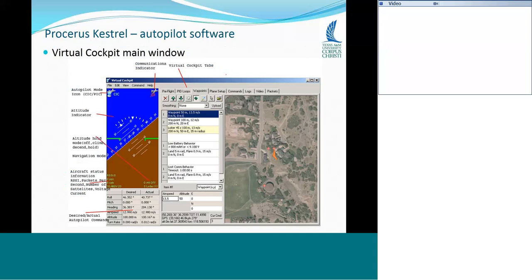Okay, so this is what that window looks like, the graphical interface. So you see the heads-up display on the left, which shows the attitude, pitch and roll. Then there's a moving map display on the right that shows the waypoints and shows where the airplane is. In the middle it shows the waypoints. And so notice there's waypoint and loiter, then maybe there's a low battery indicator. So these are some indications, but also it's talking about going through the waypoints. So notice the landing at the bottom. I think at the very bottom in the middle is where you actually enter the waypoints.